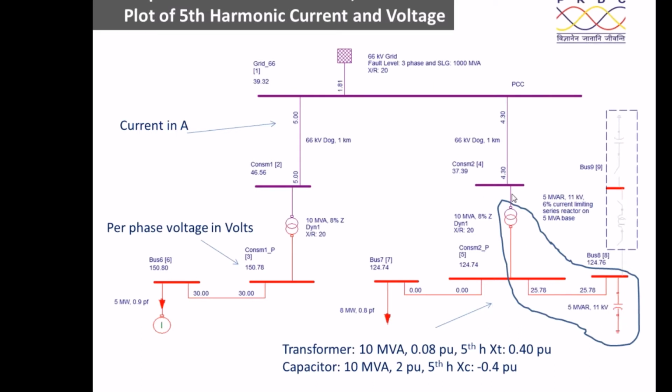He is a very nice consumer, no fault of his, but the fifth harmonic current injected by the neighborhood person is being absorbed here. What will happen? He will have an additional heating effect in the transformer, additional losses in the transformer. There will be an overvoltage in the capacitor bank, and this capacitor bank,